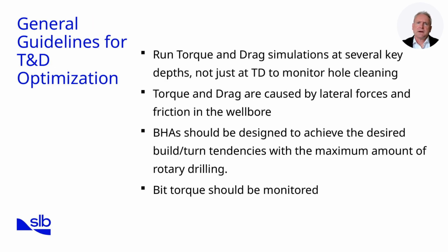Here are general guidelines for optimizing torque and drag. First, run torque and drag simulations at several key depths, not only at TD. This helps track hole cleaning and predict drag progression. Limiting analysis to total depth can mask intermediate issues, such as cuttings beds forming mid-well.